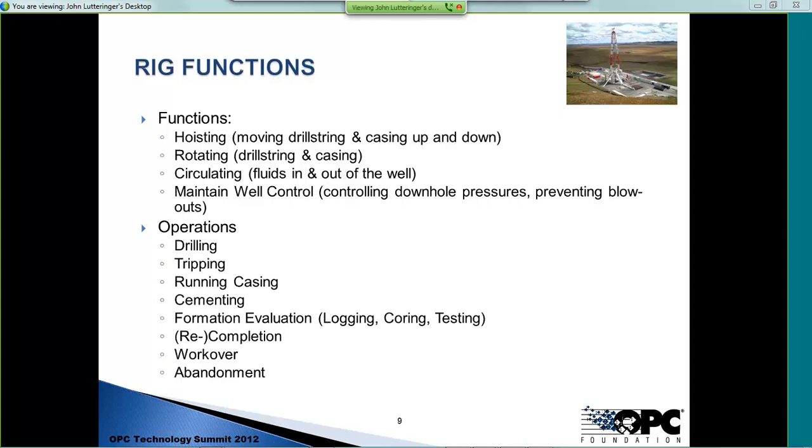The casing is a little bit smaller than the diameter of the bore of the well, and so cement is injected, and that cement fills that location in between the casing and the outer wall of the well bore. It's there to cement that casing in location and prevent it from moving around, and to prevent any water or anything external from a formation leaking into the well itself.